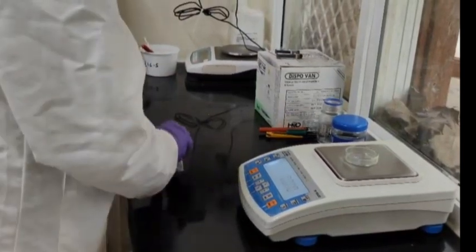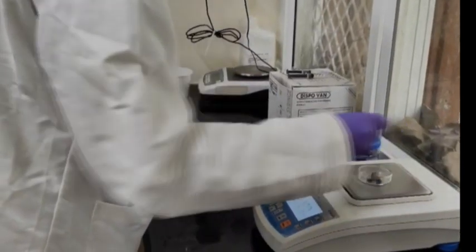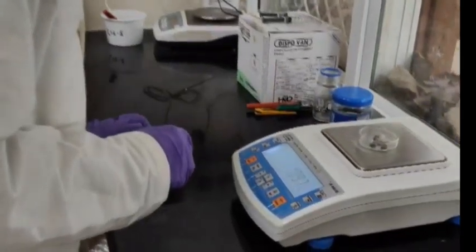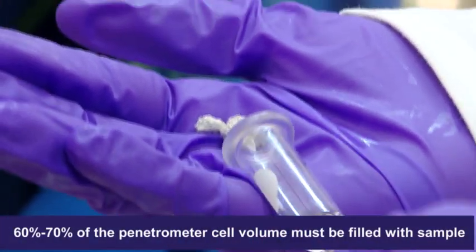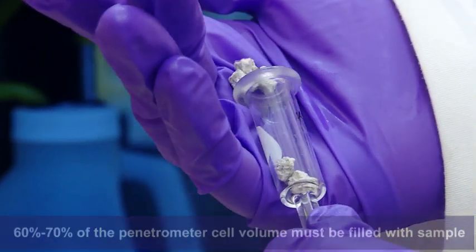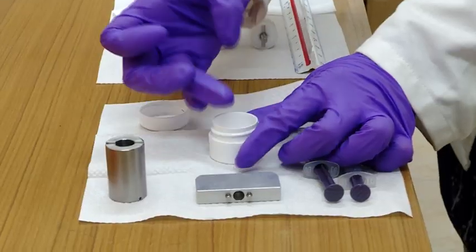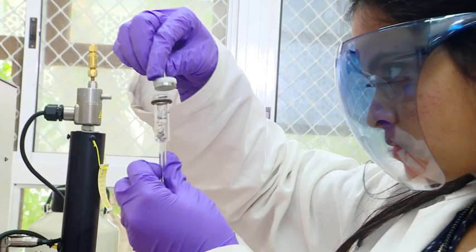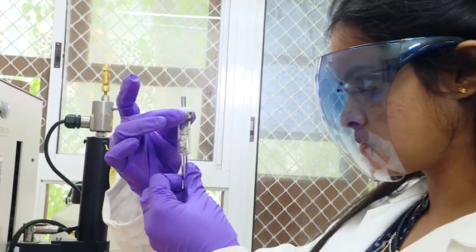First we have to weigh the sample. The sample should be small chunks of about say 5 mm or 7 mm wide. Here we have taken a sample of stone of adequate size and amount. 60% to 70% of the penetrometer cell volume must be filled accordingly. Slide the O-ring to the cell and evenly apply a thin film of silicone grease to the rim of the cell. Place the cell contact assembly on the rim and twist it to maintain a very good seal.